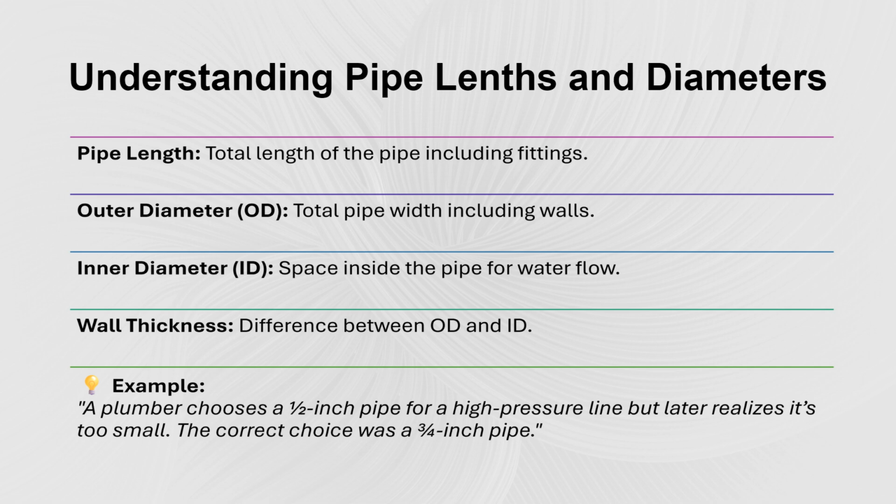4. Fourth, make sure your pipe is supported and stable. A shaky pipe leads to crooked cuts. Pro tip: use a marker with a fine tip so your lines are precise, not fat and messy. A poor mark leads to a poor cut. This step looks simple, but it's where precision begins. Every perfect system starts with a perfect cut, and every perfect cut starts with a proper mark.